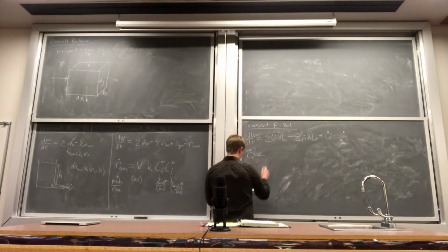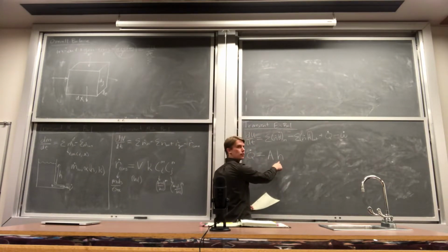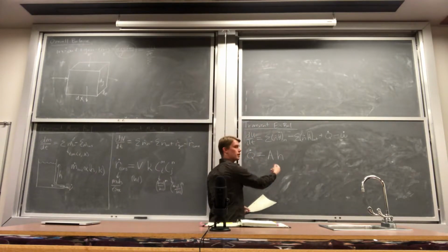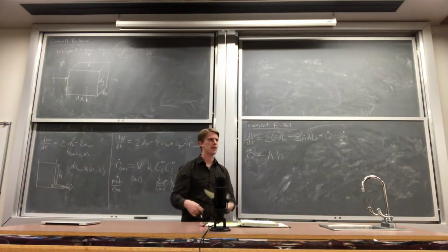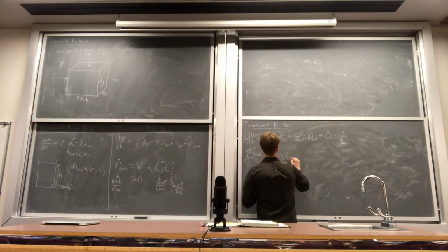And how we mathematically represent this is the rate of heat transfer is going to correspond to the area available for heat transfer times a heat transfer coefficient. This describes the conditions: what is the pipe made of, how quickly are the fluids flowing, what are the materials of the fluids, and then times some temperature difference.